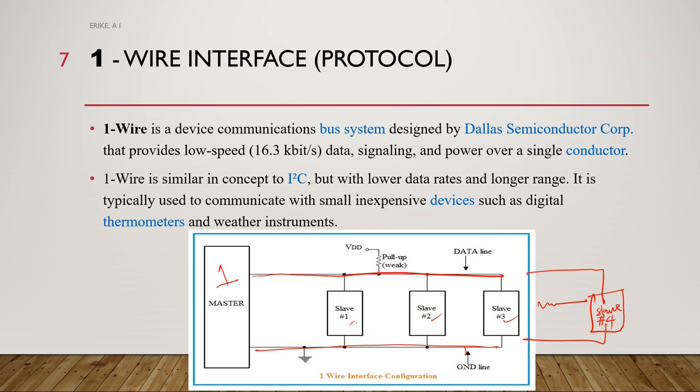So if a slave wants to send a 1, it doesn't indicate anything, it does nothing, giving the master the signal. So if the transmitting slave wants to send a 0, it pulls the data line to ground for 60 microseconds, and that is the way the communication goes from master to slave in the one wire interface.